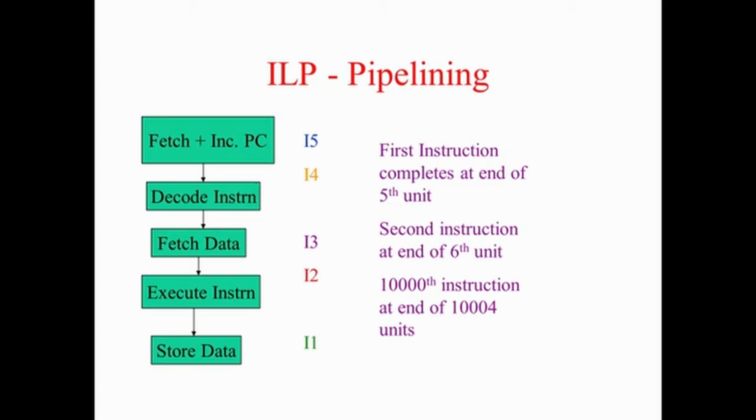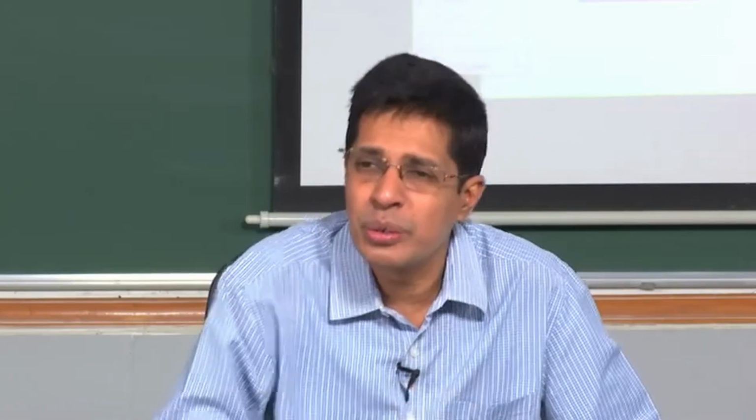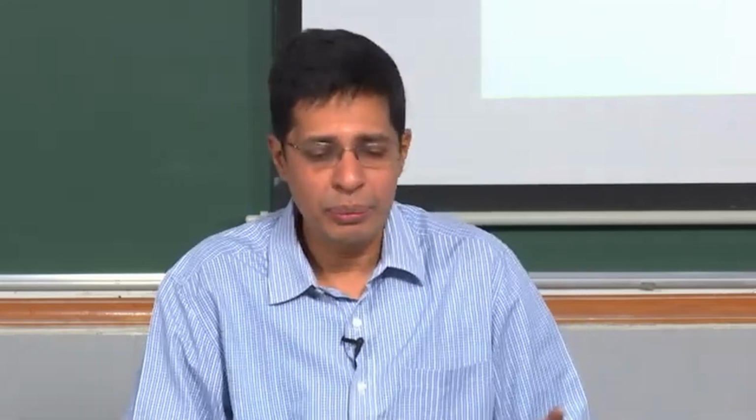So I get this 80% speed up just like this by reutilizing the hardware. But this is a very ideal case. There can be a lot of scenarios where this cannot happen as nicely as this. If everything could happen as nicely as this, then we don't have anything to teach. But a lot of problems come up when we try to do this instruction level parallelism. So with pipelining, we actually get a speedup of close to 5.